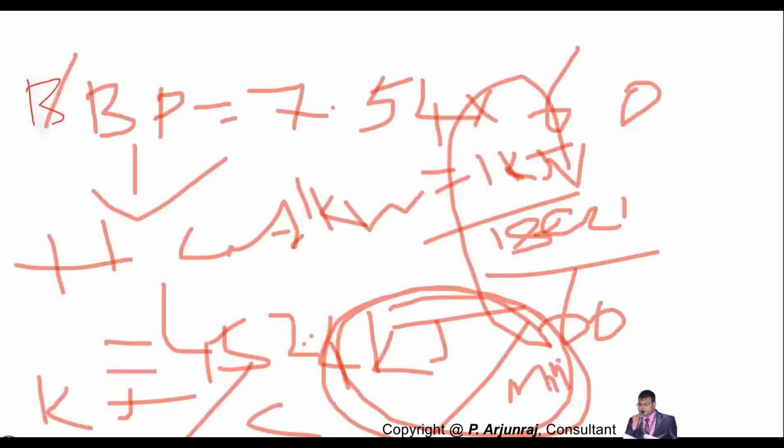Okay, so this is one form. I told you 100 should be equal to 100, meaning the energy supplied should be equal to that of energy distributed. So we are getting only 452. Okay, the remaining have a lot of things. We also need to calculate the heat loss because of the cooling water, the heat loss because of the exhaust gas, and also the unaccounted loss. Okay, so next we will see the heat loss because of the cooling water.